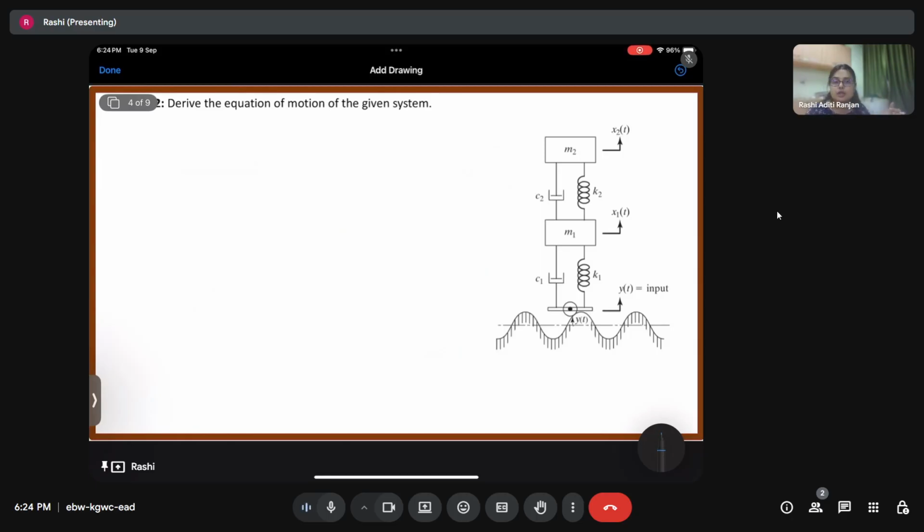Now Lagrange equation was again used for a conservative system. For a non-conservative system, we had to define the Rayleigh dissipative potential, and then we had the principal forces Q1 and Q2 that we can use in order to include the effect of any kind of forcing. But over here, we don't have the direct forcing, F1 or F2. Instead, we have the displacement input. So we'll prefer using the force balance method over here.